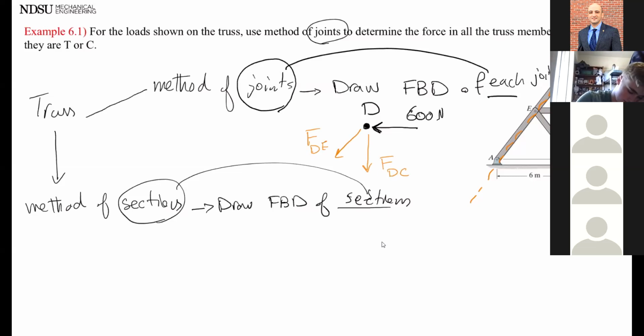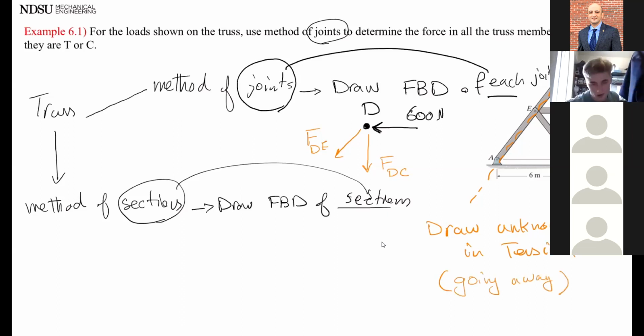And here's my method all the time. Draw for both of these, draw unknown forces in tension, meaning going away from the pin. Okay.